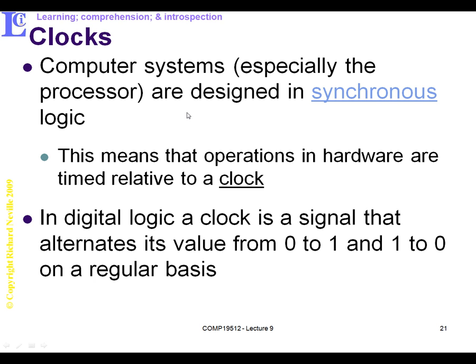Now, actually every single operation in these processors is in lockstep. That means that you must align to a particular signal for everything you do when you're talking to the processor. The terminology for that is synchronous, and that means it must be timed relative to the clock. So there's a clock, and if you remember, I talked about that when I talked about the motherboard, and the processor is connected to a clock, and there will be a clock line coming to the processor which drives it at a particular frequency, and everything happens in lockstep with that clock.